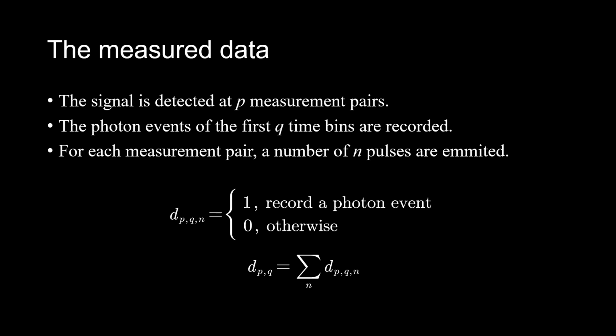In non-line-of-sight detections, the intensity of the back-scattered light is extremely weak after multiple diffuse reflections, making it impossible to measure the photon intensity directly. The recorded data are actually photon event stampings. For each measurement pair, n laser pulses are emitted to the illumination point and the recorded time-resolved photon events are denoted by Boolean variables. By counting the photon events of each measurement pair in time bin, we obtain the photon event histogram, which approximates the value of photon intensity.